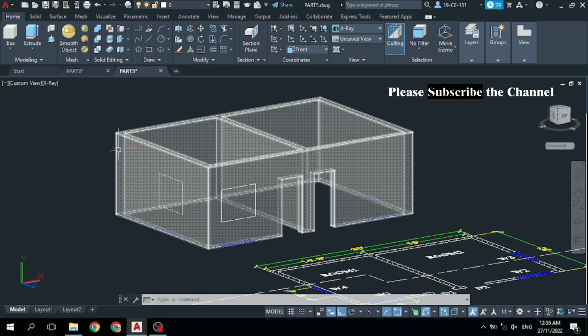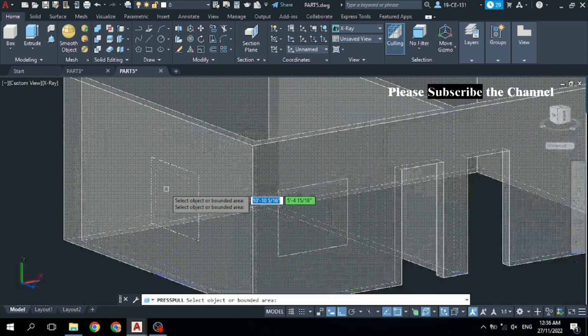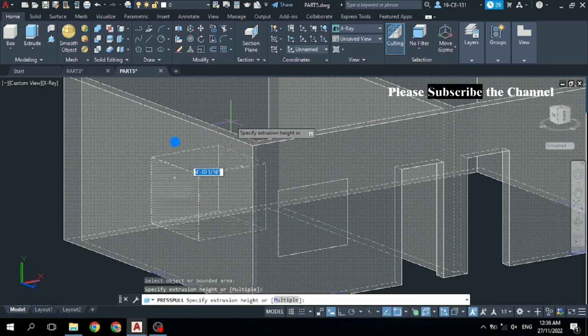After completing this, now I would like to click on the Press Pull command and click inside this window frame. Simply click inside this window. Now you can see the cursor selects it, so simply click inside, do not click at this edge, simply click inside and go some distance to this side, to the back side, and your distance must be more than the width of this wall.